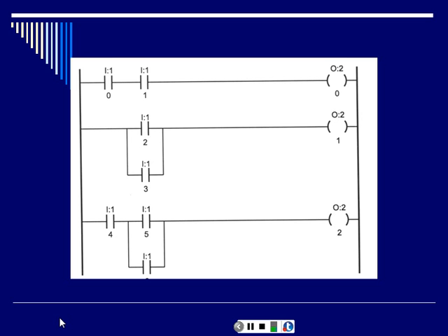So if this guy's not working, I go to the mushroom push button on the shop 4 wall, find it, and I can hit it and see if that push button's working, or I can actually ohm it out to see if it's working, or put the voltmeter on it and see if I have voltage, and push it in and see if I don't have voltage. So I can now do something with this push button.